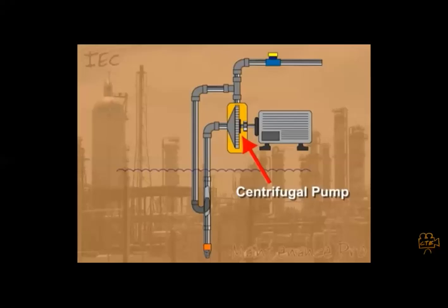Before starting the jet pump, you can't start it directly. You have to fill both pipes initially with water. Only then it will work. You can't just put it down and start your motor. You have to fill this with the water.